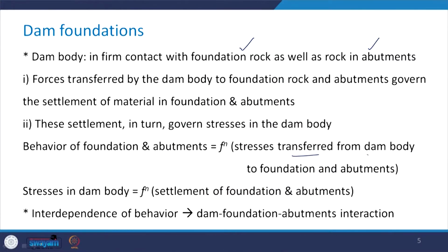See, the load is coming from the dam body to the foundation rock and the abutments, and the settlement is going to take place. The moment there is a settlement, this results in the redistribution of stresses in the dam body, and therefore the behavior of the foundation and abutment becomes a function of stresses transferred from the dam body to the foundation and the abutments, and the stresses in the dam body become functions of the settlement of the foundation and the abutment.